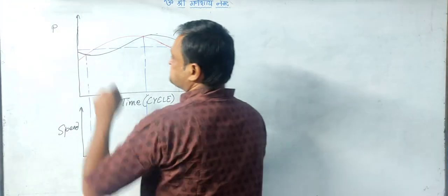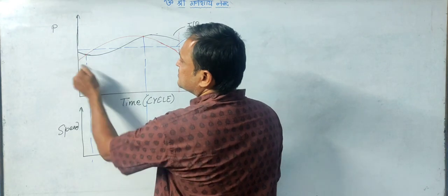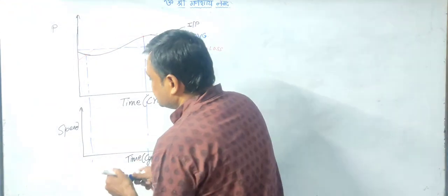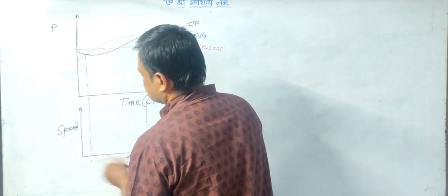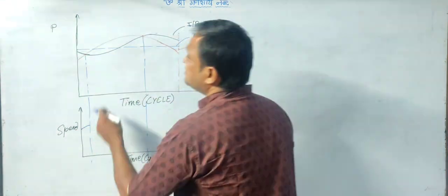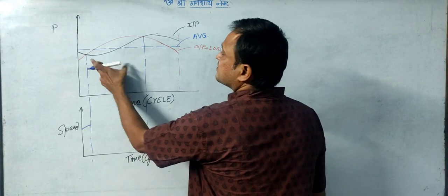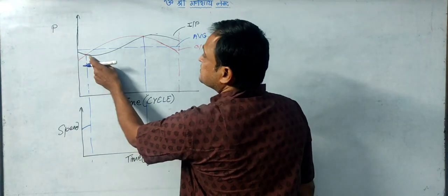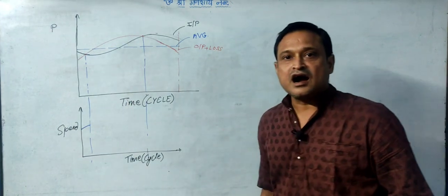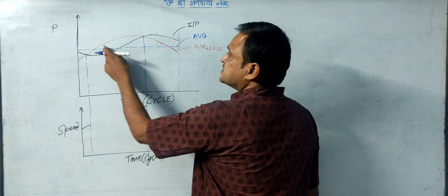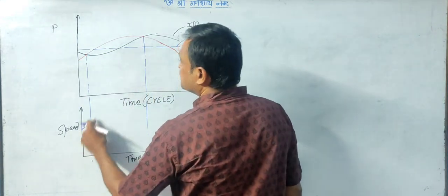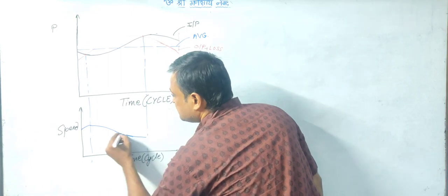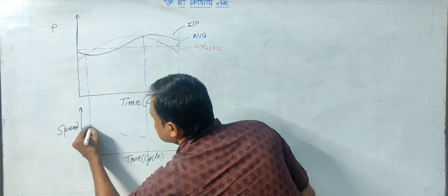But what about this situation? Here, at this portion, the input is more than the output that is utilized. Say this is that speed. Now from here to here, from this cycle position to this position, you will see that the input is less than the output, or the supply of energy is lesser than what is required. That means from this position to this position, the speed is going to drop, right? Maybe it is dropping this way. So the speed drops,